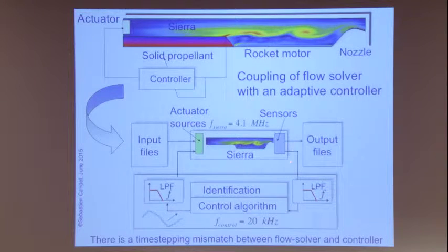The time step is much smaller because you need it from the fluid mechanics point of view. So what you have here is to bring these signals from here, and it's important that the signals are low-pass filtered so that, if you keep high frequencies coming from this and you send them at a low frequency here, you have a problem. So there is a low-pass filter to place here. If you don't put that, this sort of simulation doesn't work well.